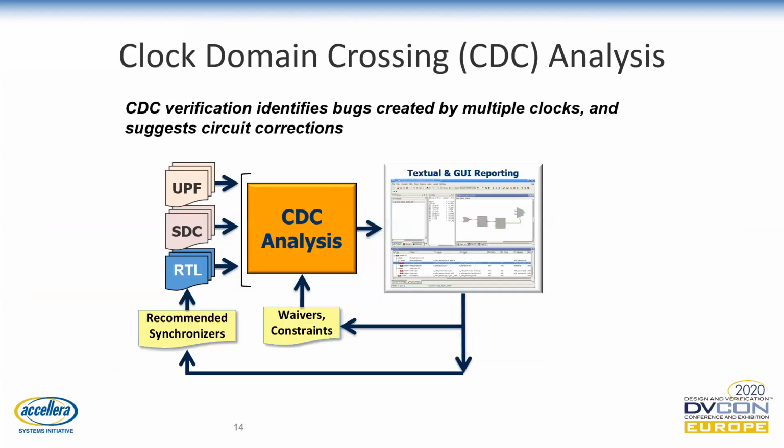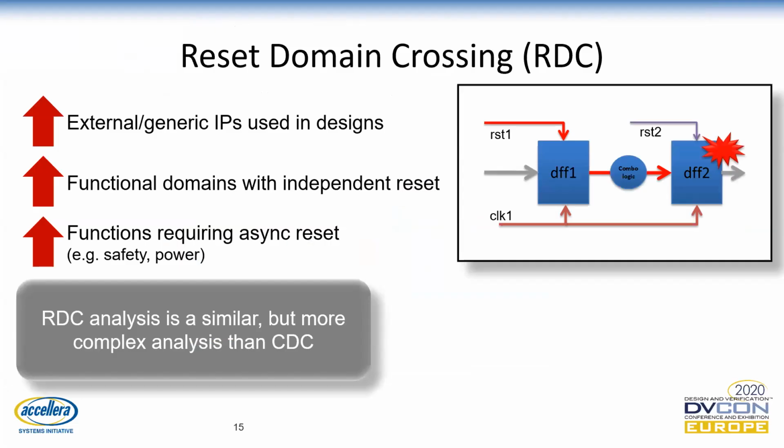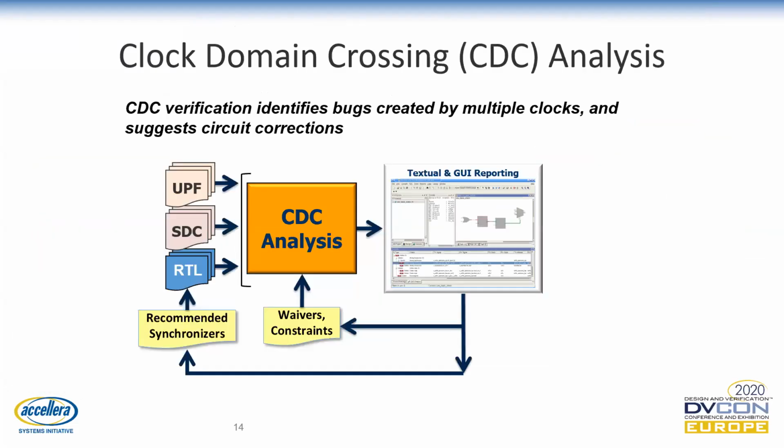As FPGA designs get more complex, the number of crossings exceed the limit of what can reliably be reviewed by manual design reviews. CDC analysis tools enable the automation of manual CDC reviews. For CDC analysis, constraints enter the flow for the first time.